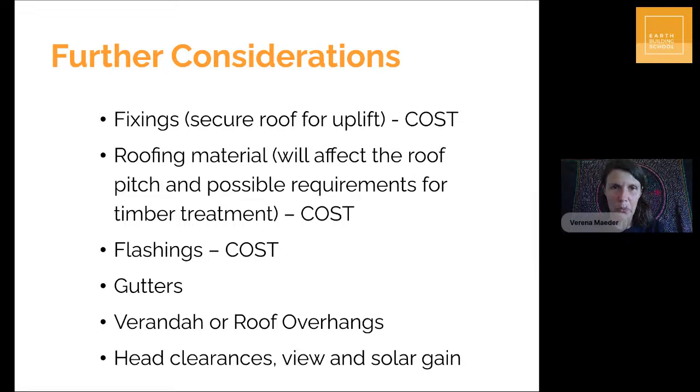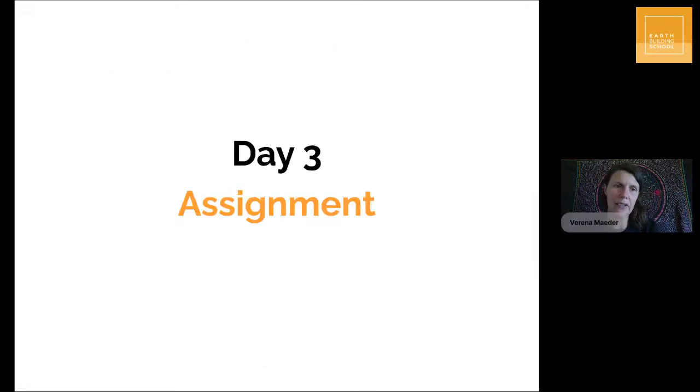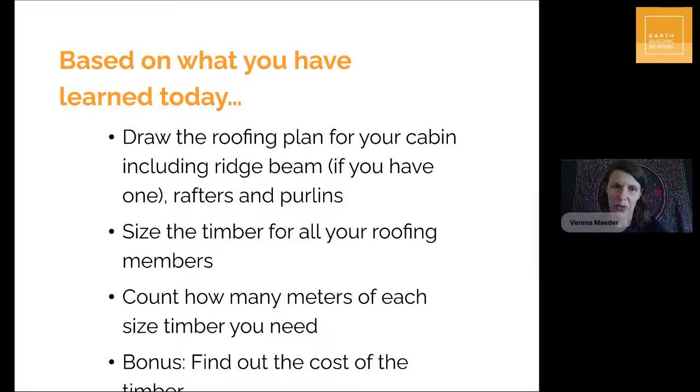So tomorrow we will go more into sections of buildings, and we will really start thinking three-dimensionally and making sure that those things work. But I'm already inviting you to start thinking about this when you're drawing or conceptualizing your roof plan, and inviting you into thinking about the roof plan today. So think: what kind of shape of roof do I want? Is there a ridge beam? And then sizing, if you have a ridge beam, the ridge beam, but at least size the rafters and the purlins.